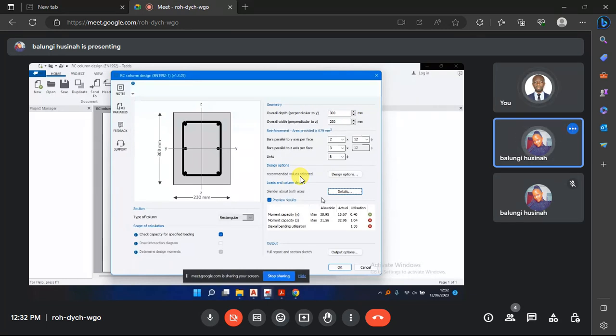I think I prefer increasing the bar size, because increasing the shape means I have to go back and edit my drawing to put a bigger column. I go and change maybe the beam design. No, I prefer changing bars. So make it 16. Make it like 16.